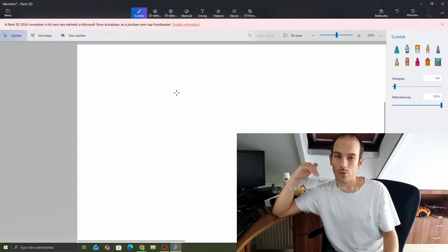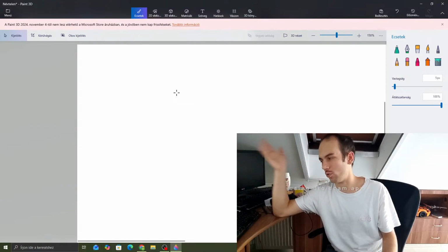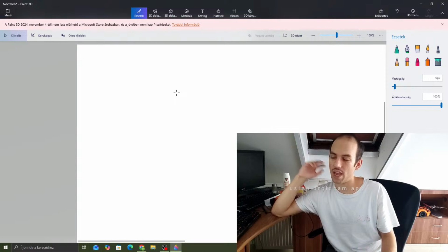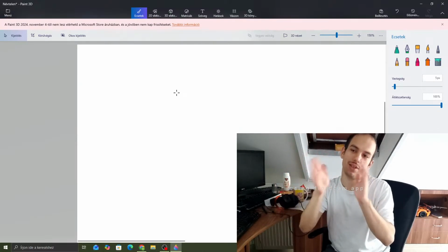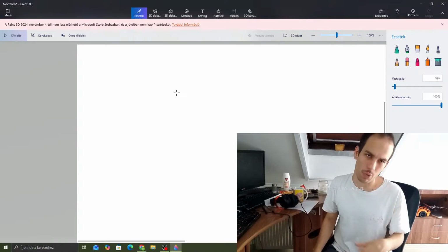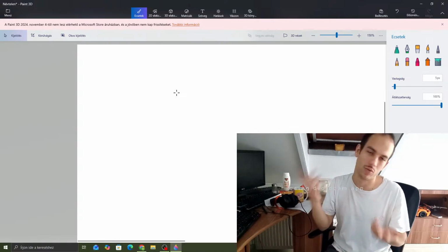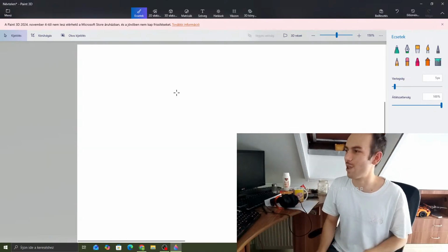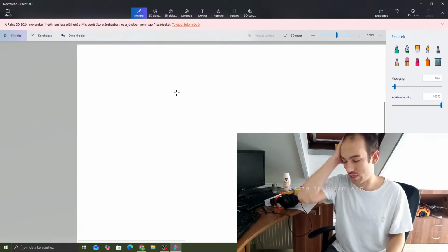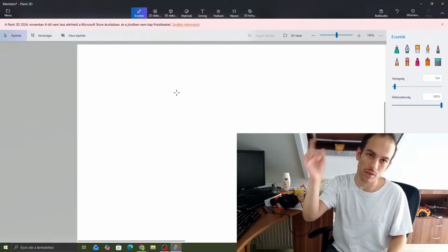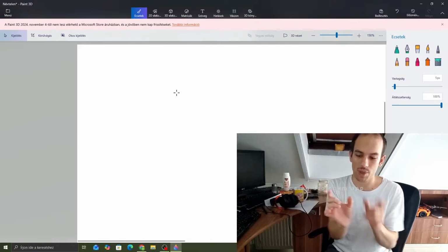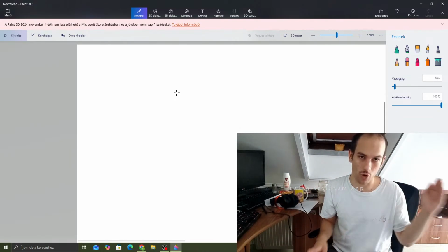Then I'm going to create plots like the ones I have shown, and from the plots we are going to determine if the current sampling time, 2 hertz, is good enough. 2 hertz means every second there are 2 measurements, so half a second, 500 milliseconds, between each measurement of pressure.